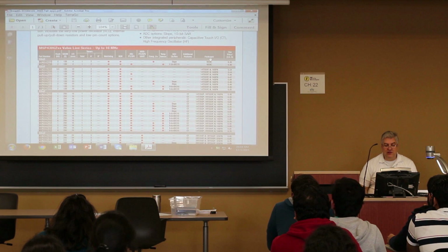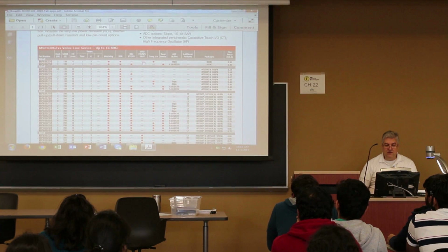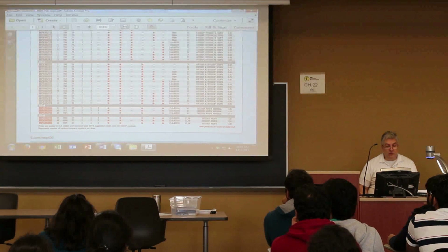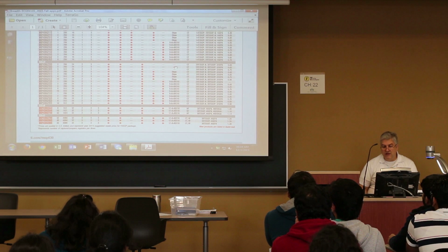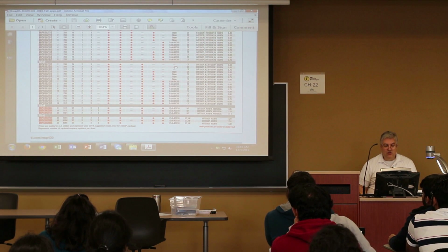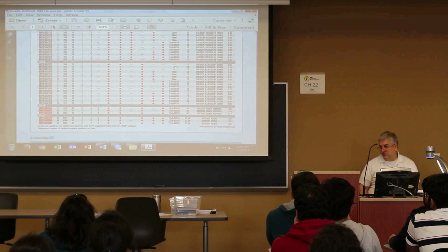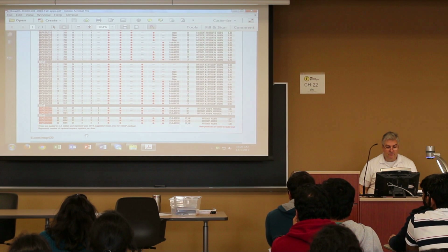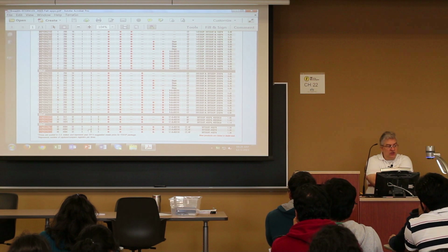So what did we say we definitely need this thing to be able to do? UART, all right? So do any of these chips have a UART? All right, so obviously those are discounted immediately. And it's only the ones down at the bottom, all right? Do we care anything about this column, this column, this column, the A to D? Not really, so we don't care about that, all right? We do care about the number of timers it has, and we identified we needed 2, right? So, do these have 2? Oh yeah, they have 2. And how much memory do you think we need?